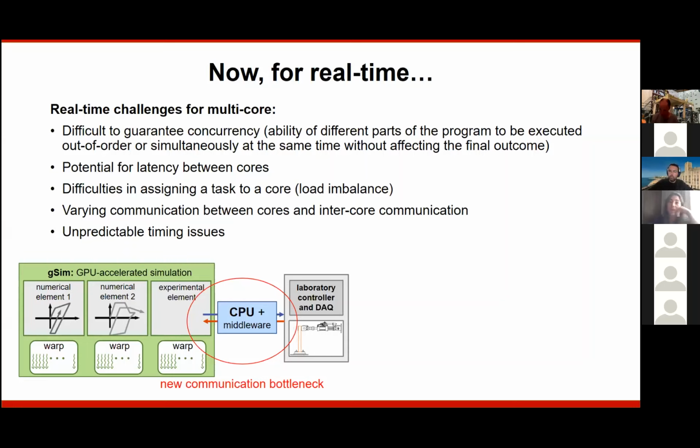Somewhat, it's really more of the element formulation. So GPUs do really well when they're doing the same thing across a massive data set. They're really good at that. And so if you think about really finely discretized problems like fluid mechanics, where you have to have a very fine spatial discretization, then each of those elements are having the same instructions, and that can all be done at once. And so the GPU is really good at that.